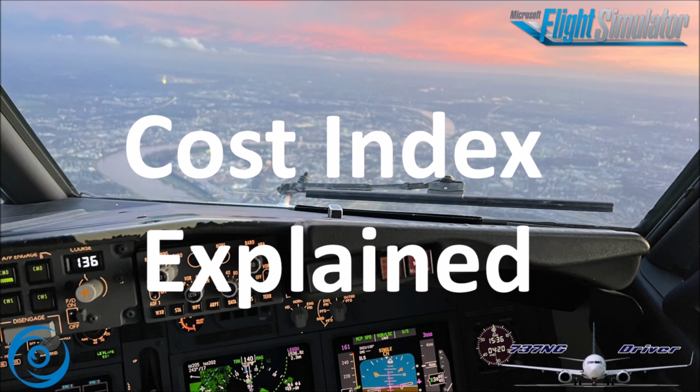You can actually find out the amount of time that you may be able to save by looking at the RTA page on the FMC. So that's from the progress page. You go on to page number 3 of 4, and then you just enter the destination runway as the RTA waypoint. So, for example, when you're still standing on the ground and you were to fly to, let's say, London Heathrow with a landing runway planned of 27 left, then you could enter Romeo Whiskey 27 left as the RTA waypoint on the RTA page.